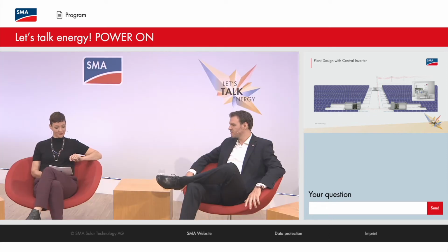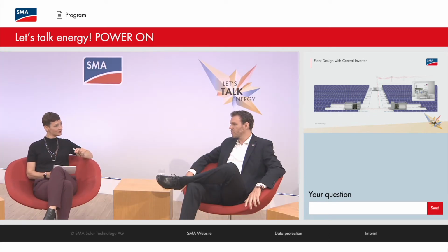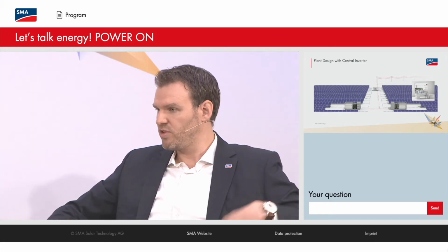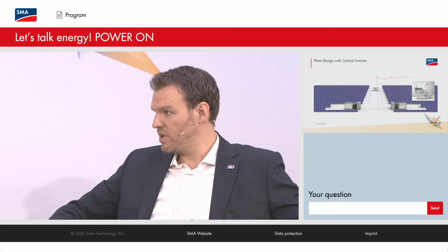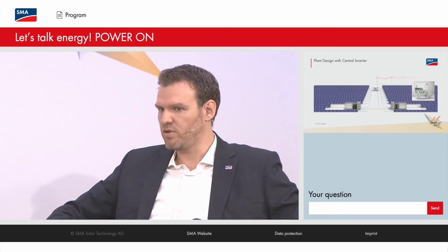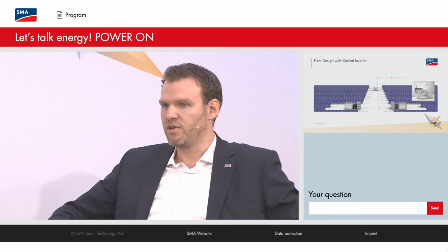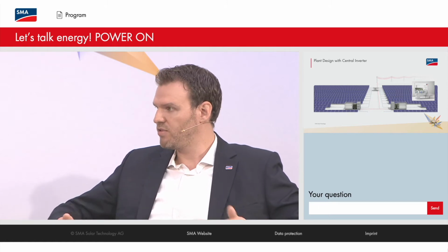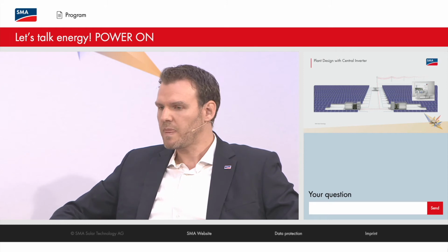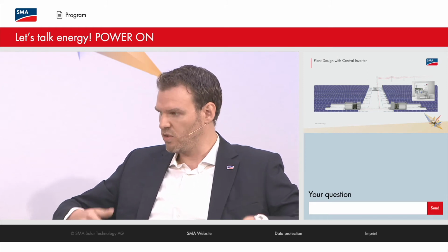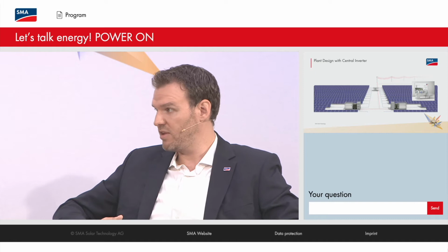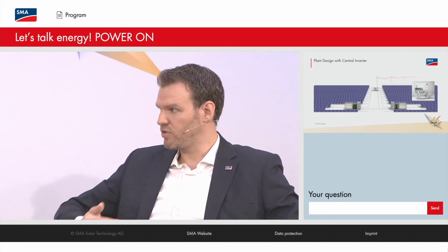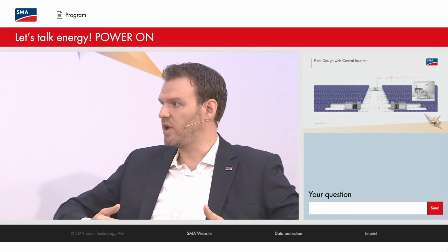And can you give us an important factor for the system design, please? So something which has really changed over the last 10 years is the design ratio. When we started the industry, solar panels were extremely expensive, and usually space was a constraint, especially on rooftops. So the design ratio was very moderate, maybe 100% or 110% DC to AC. But this has changed, especially since we're going to markets where we have restrictions on the AC side. So you cannot add additional inverters, but you can potentially add more solar panels, which further increases the design ratio.